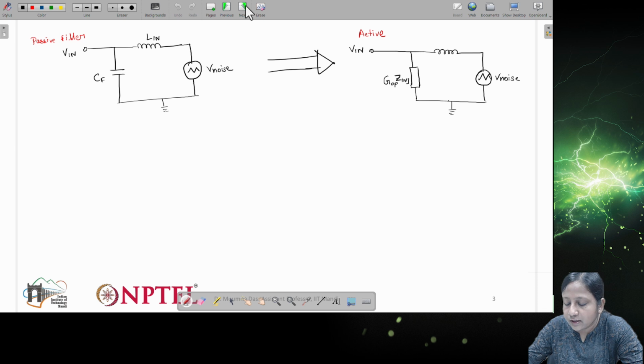So ultimately it remains the same. The noise here, V noise, will be variable with respect to voltage, current, power level, frequency level. Like in your system, if the voltage is variable, let's say you are using it for an application where you need the voltage to be variable, then the noise level will also probably vary. And in case the power is variable, generally it is not constant, right? So then the noise level will also vary. For some applications we actually use frequency control, so then frequency changes, right? So then the noise will also change.